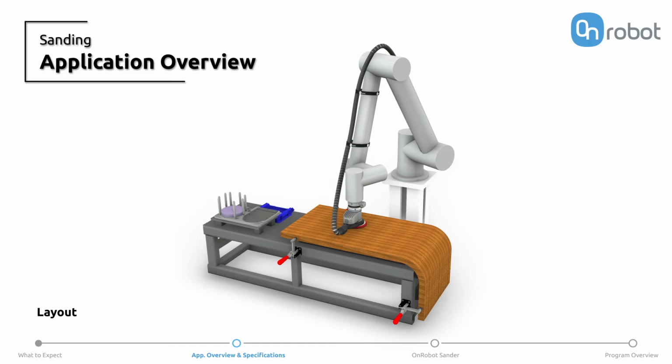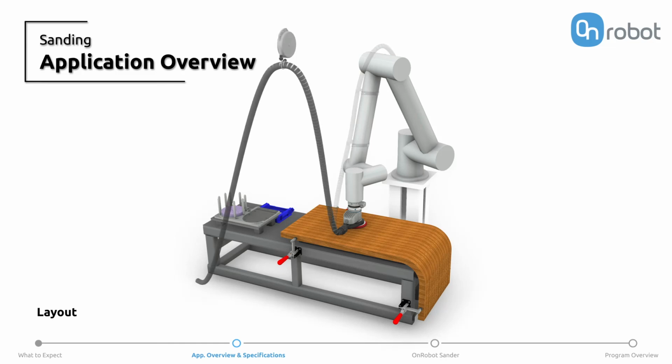Ensure that the vacuum hose is fully secured and won't become tangled, as this could disconnect it and cause a hazard. If, while sanding the workpiece, any of the robot joints are expected to rotate considerably, it would be advisable to use a spring balancer to hold the vacuum hose rather than secure it around the arm. Regardless of how the vacuum hose is attached, avoid having it pull the arm with great force, as this could negatively affect how the robot follows and conforms to the contour of the surface.